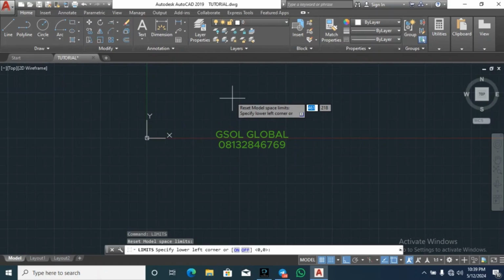So now I'm not going to be inputting and taking them back to the origin from this place. From my keyboard, I'll just hit the 0 for the first one with the x direction. Then I hit the tab key, then 0 for the y direction. So now it's taking us back to origin.